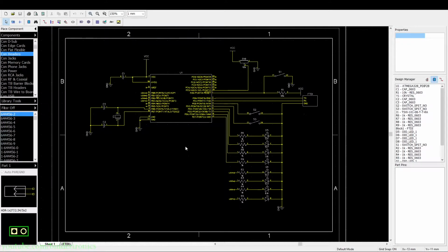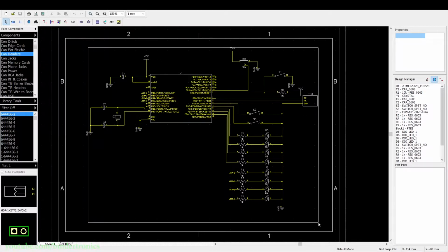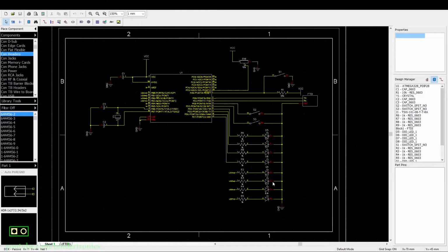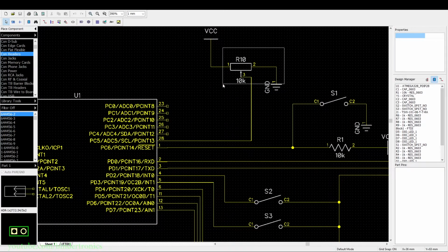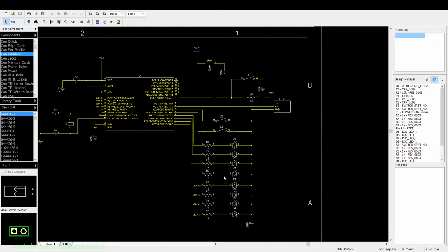Hello, and in today's ATmega328P programming, we are going to set up a timer base. So let's have a look at the schematic. The schematic is effectively the same one as the previous tutorial from the ADC. We still have the 8 LEDs that we use for a display output. And then we are going to use the analog pin with the 10K pot. And the 10K pot is going to set the blinking intervals of our LEDs based on the internal timer.